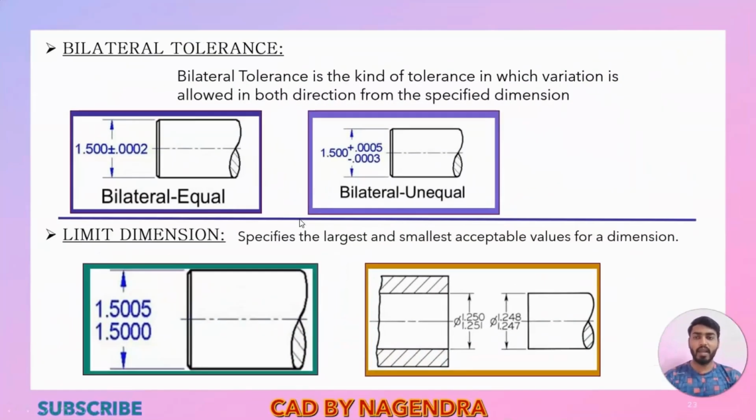Then next we have bilateral tolerance. Bilateral tolerance is a kind of tolerance in which variation is allowed in both directions from the specified dimension. Unilateral means only the positive side or negative side gets variation. With bilateral, the name itself has 'bi', so two sides. A positive value will be there, and a negative value will be there.